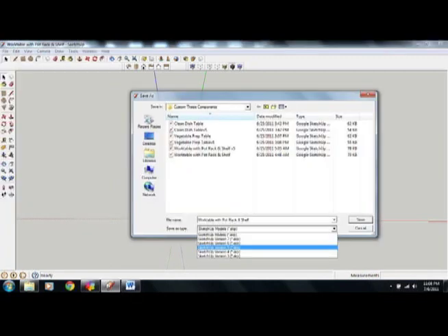Once you are done with your SketchUp component, click File and select the Save As option. At the Save menu, select SketchUp version 5 from the File Type drop-down menu. Newer versions of SketchUp files are not supported in Revit. Name the file and click Save.